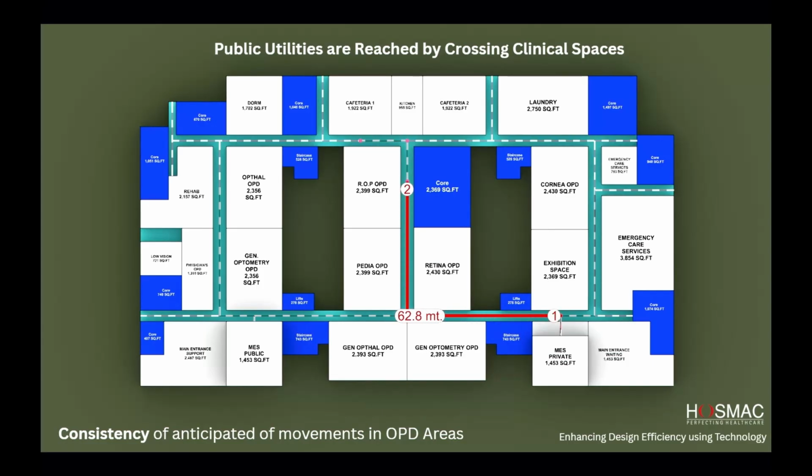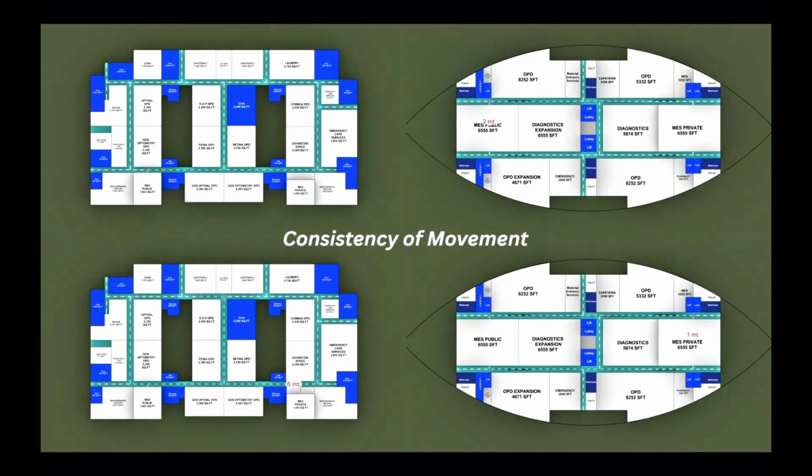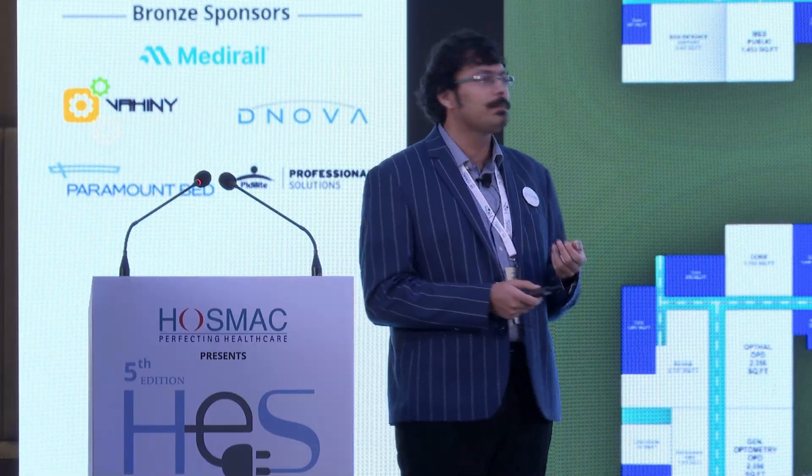So public utilities were being reached by crossing clinical spaces, which we also try to avoid by ensuring that public utilities are not reached by crossing clinical areas. Rather, they are adjacent to the clinical spaces, so that no matter where you are in the building, from a common point of confluence, you can reach them in a streamlined manner. So consistency of movement is also important to reach the efficiency of design quality when you plan a hospital building.